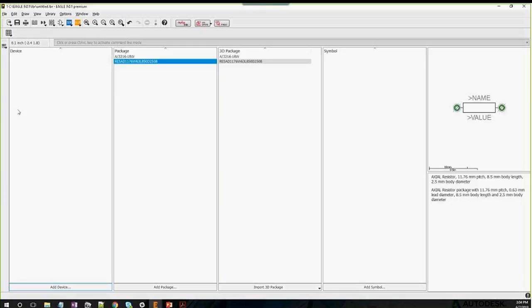As long as the pad or SMD is within the polygon, Eagle sees the polygon as an extension of the pad. The solution is not 100% ideal because you still have to manually draw in the stop mask and the cream mask, but that's the solution we have for now.